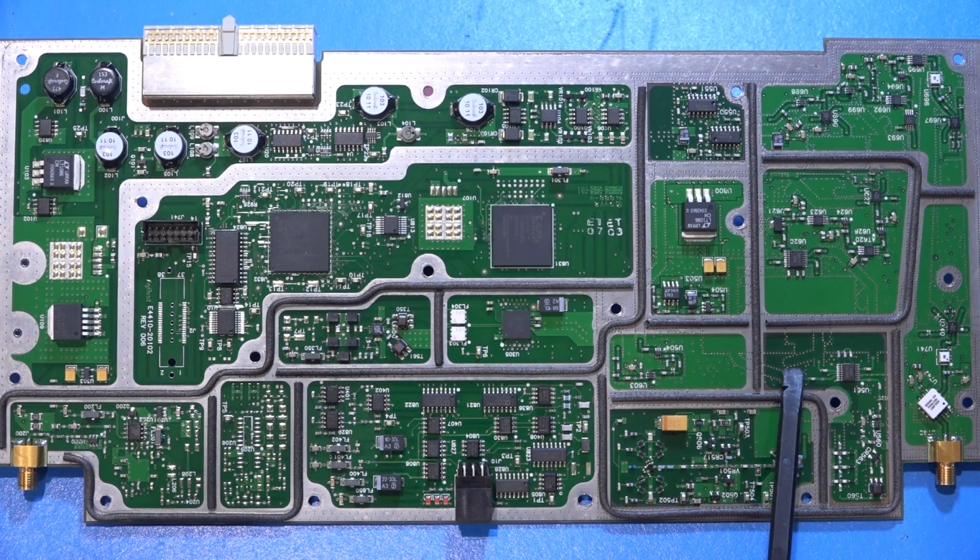Often you see hairpin filters or various bow tie resonant filters and things like that on the surface of the PCB, but they're actually not on the surface here, they're in between the layers. That's for various reasons, for space and for being able to isolate them and so on. And then there are several filters. All of them have to come together eventually, and they come into this selector switch.